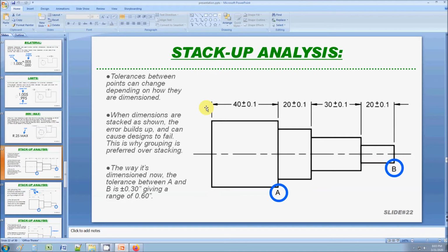So you can see how this could be a problem. Think of an engine block that has all these parts that are connected in 3 dimensions. You can see how this could be a stack-up nightmare of parts that could fluctuate in any direction and give you all kinds of problems when you assemble it. And this becomes more of an issue when you are producing millions of these products and going up against all the possible scenarios and Murphy's rule of the worst that can happen. You can see how this can really be an issue.